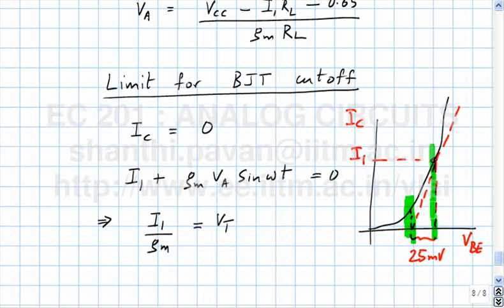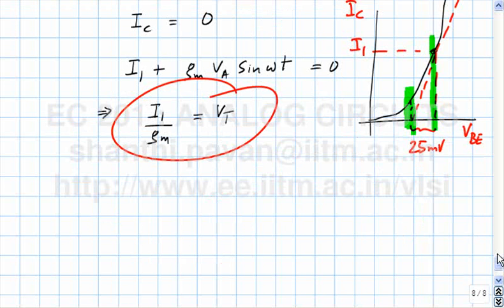The current has not gone to 0, but it is reduced so low that the Gm of the transistor has gone down by a factor of 3. So the incremental gain has also gone down by a factor of 3. So you will see a flat top. Same stuff that we encountered in MOS circuits. You understand? So with this, I think I will call it.